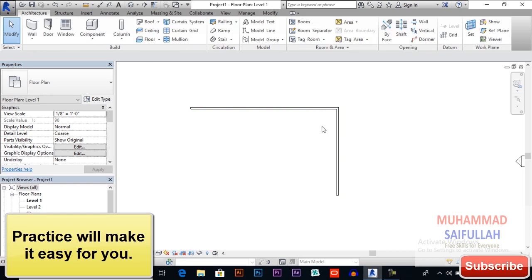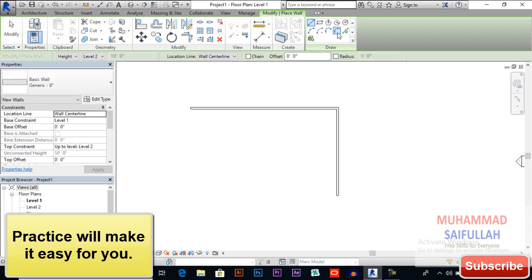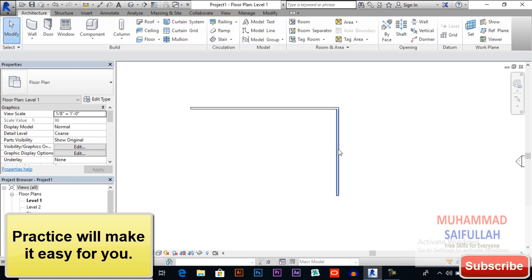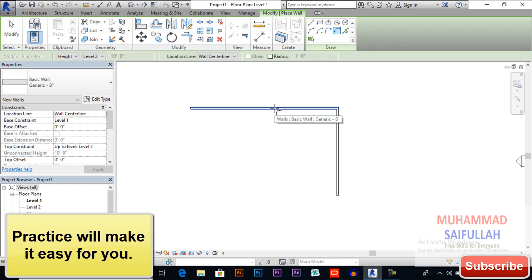So if you have this kind of wall corner, then you can draw a fillet arc from here. Select this line and then select this line. Draw it again. Select this line, drag it here, and you can see. So I will click it again. So you can give a fillet here. If you have problems, you also can give a fillet.